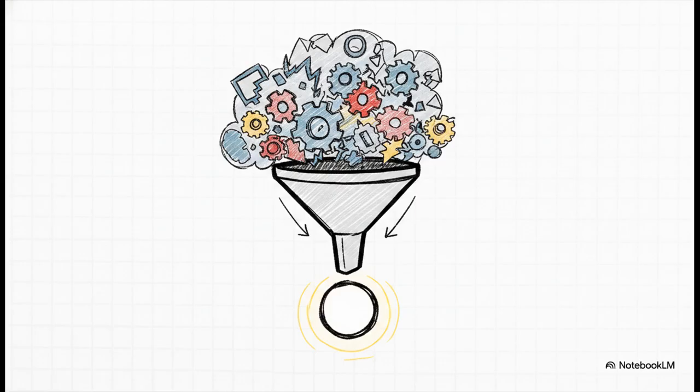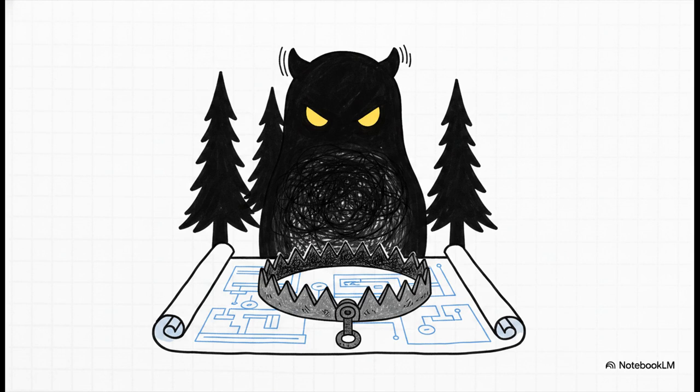What you're left with is a universal, dimensionless per-unit value that you can cleanly analyze side by side with equipment operating in a completely different voltage zone across the grid. But hold on a second. I need to pause here and issue a massive warning. If you're analyzing grid data, there is a literal monster in the woods waiting for you, and it's called the change of base trap. I'm using a serious tone here because skipping or forgetting this step wrecks more junior engineers' first power system studies than literally any other error.